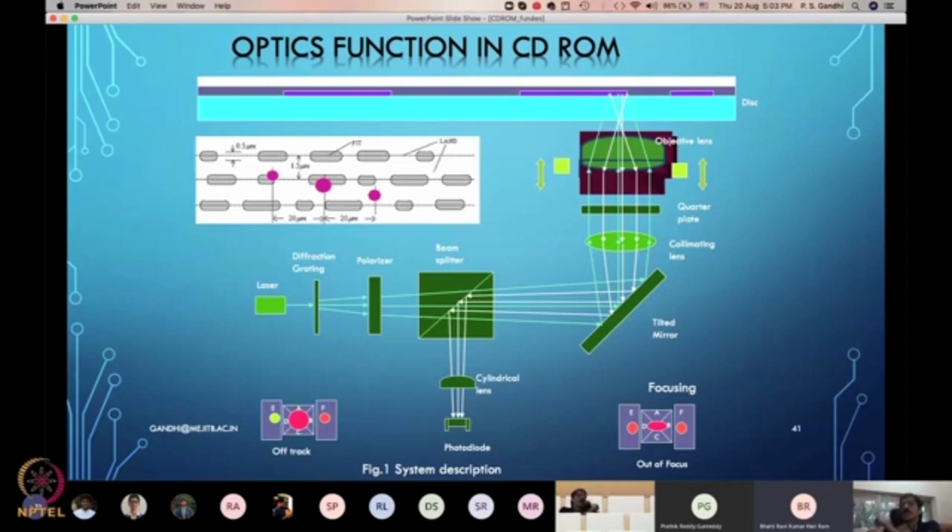So look, okay, yeah. Normally, you'll design the system to satisfy the specification. So for example, the undulations on the CD surface are designed to be maybe within say 100 microns. Then this compliant mechanism will be moving only plus minus 100 microns or plus minus 50 microns, that kind of a motion, and that will be sufficient.